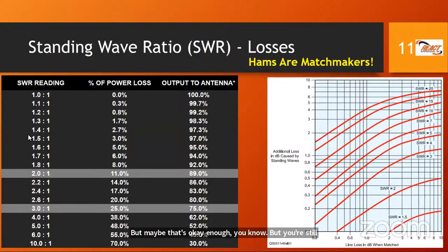So when you're constructing your antenna, and you're connecting your antenna to your radio, you're aiming to tune that antenna down to the lowest possible SWR.